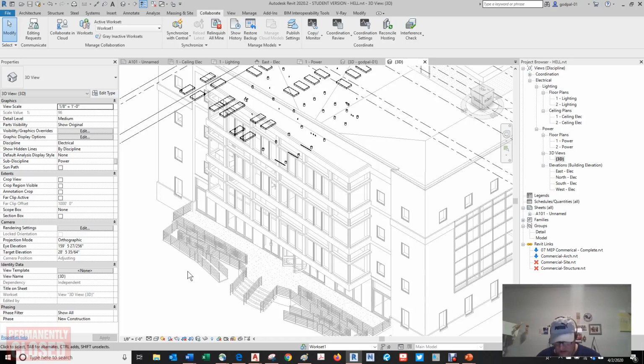In addition to levels, work planes can be defined as reference planes, a structural grid or a surface of another object. To help you visualize an active work plane, a work plane viewer is available in Revit. Be aware that an active work plane could be perpendicular to your orientation if the view is adjusted three-dimensionally.